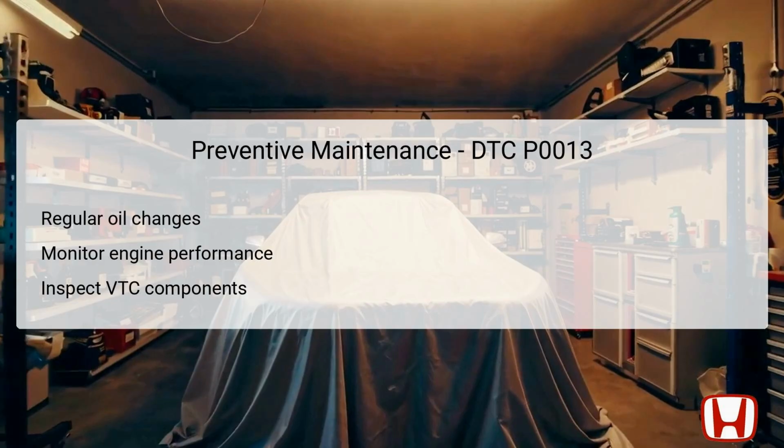Preventive maintenance is crucial in avoiding issues related to the VTC system and the P0013 fault code. Regular oil changes are fundamental, as clean engine oil is vital for the effective operation of the oil control solenoid. Contaminated oil can lead to solenoid wear and malfunction, so adhering to the manufacturer's recommendations ensures optimal performance.